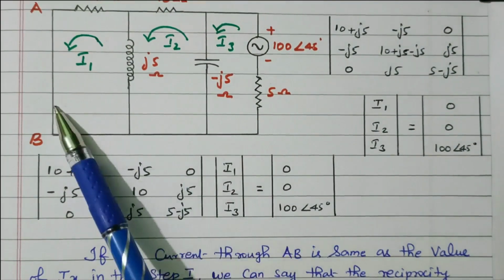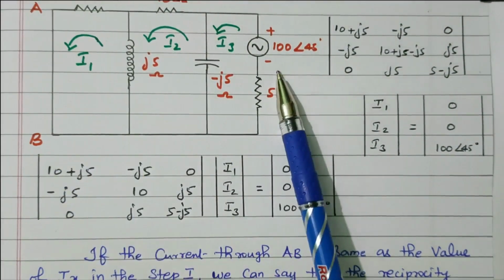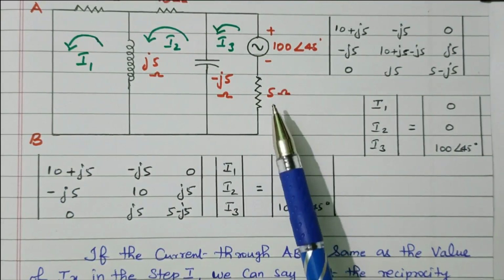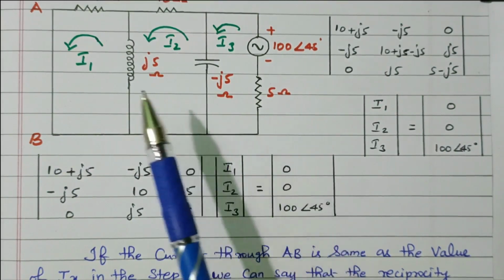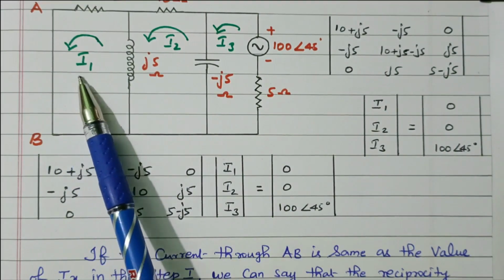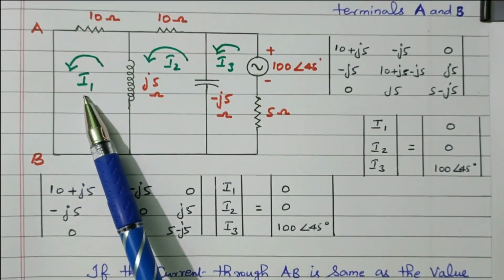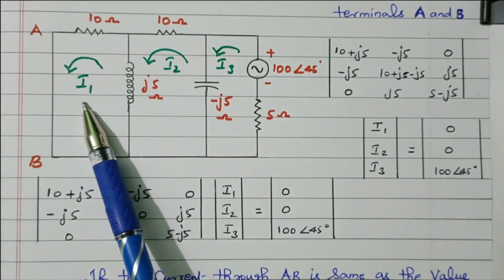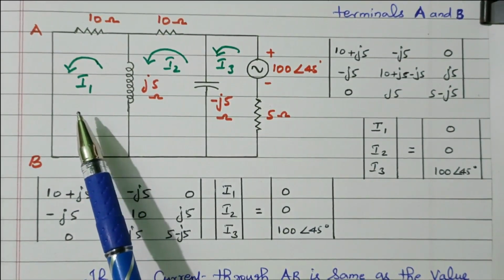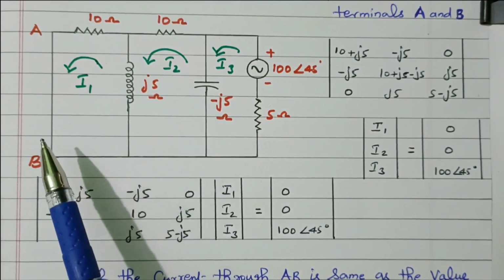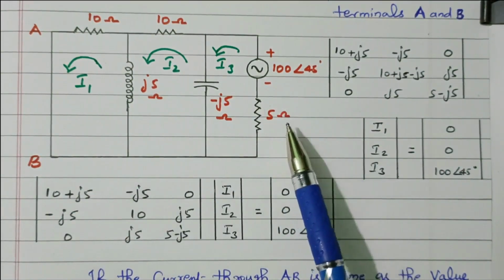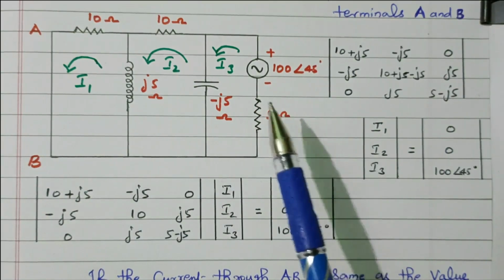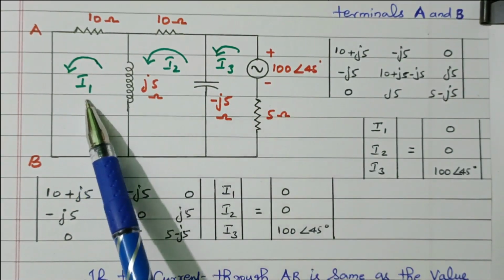Now see here, the voltage source available is now transferred to the third branch. Now we need to verify that the current in the 5 ohm branch, what we calculated as Ix, should be available in the first branch, I1. The I1 should be the value we calculated, that is 2.167. Right. So the voltage source from branch 1 is transferred to branch 3. The current we calculated should now be reflected in the first branch, that is I1.